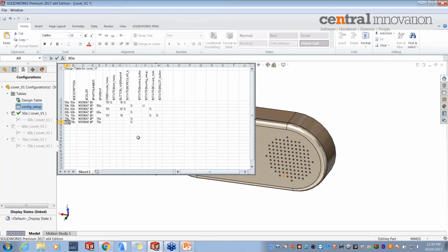And when you select a certain field, it tells you what possible commands or syntaxes it can accommodate, or you can simply use a drop-down box and suppress, unsuppress, and you can even put values in it for the dimensions which we have already linked. That could be done. That's another handy way of doing it.